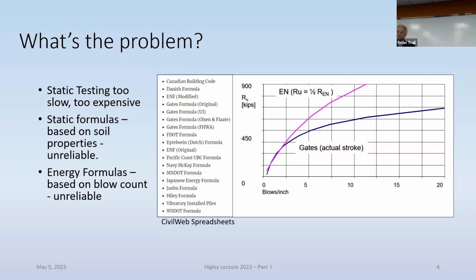And every professor that had a consulting job at a certain construction site came up with his formula. With that formula and a given blow count, number of blows per inch or per foot, you could determine the bearing capacity of the pile. And depending on the formula, you get one or the other result.